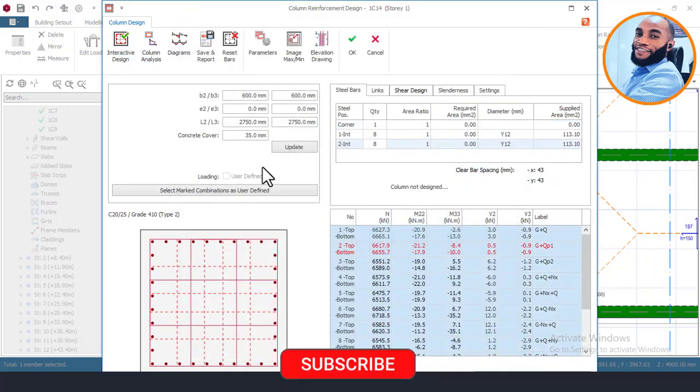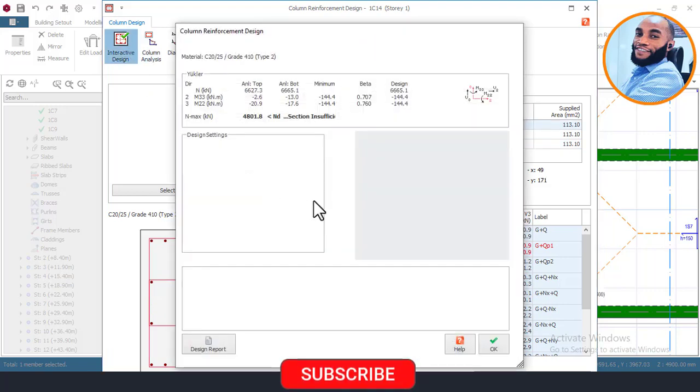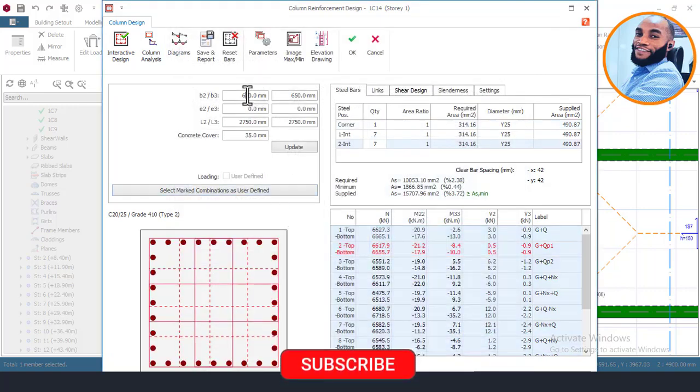I'll come here and then say okay, and come here and increase the size to 650 and also 650 here, and then click on update and reset the bars, and then come here and click on design and wait for it to finish designing for that, and that is okay. This is showing me 32 number. That's fine, I can do that. And I'll come here right now and then say okay. If I don't want to, I can go and choose 700. That's to reduce the number of the bars. But I think that's okay basically.